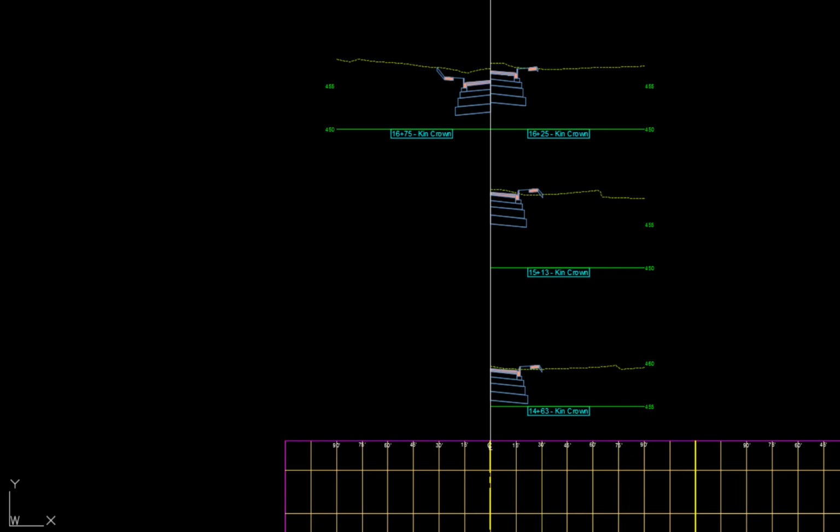Swath widths of 0 feet left and 90 feet right were used for the driveways on the right side of the road. The spacing of the left and right driveway profiles has been adjusted so that the stations are in a correct ascending order. Left and right driveways that are in approximate vicinity of each other have their axes at a common point along the vertical center line.